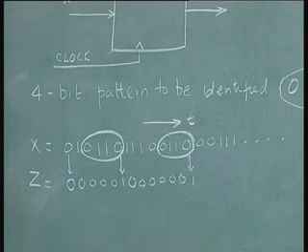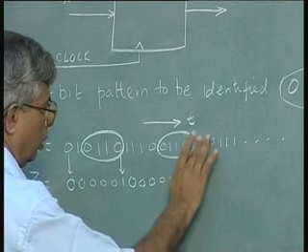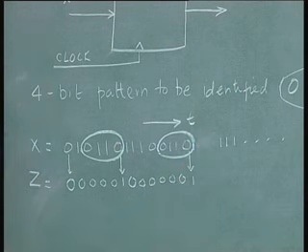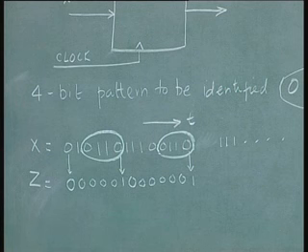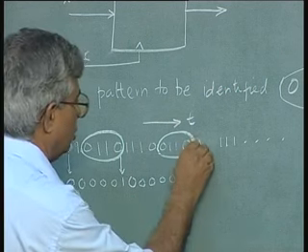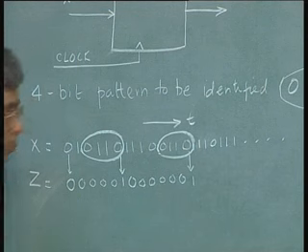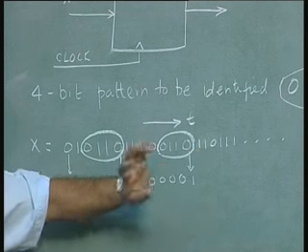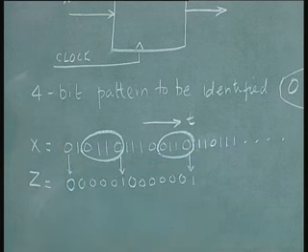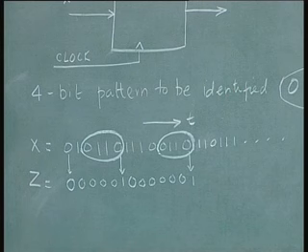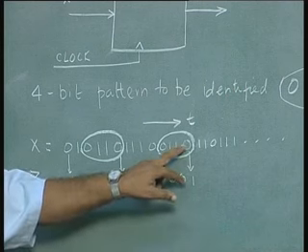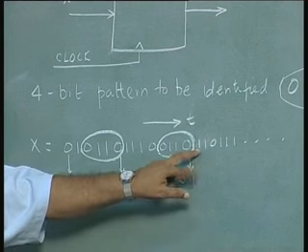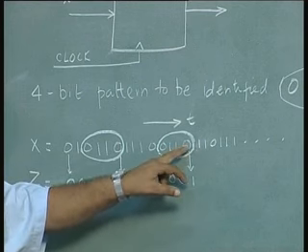let me make a change in this pattern too. I will give you an interesting concept. I will make it 1 1 0 like this. So, now the fourth bit was a 0, so a 1 occurred, then the next again is a 1. Now, the question is, as a designer you should ask this question before you start with the design. If this 0 has already occurred and this one is occurring next, should I count this 0 also into a new pattern?